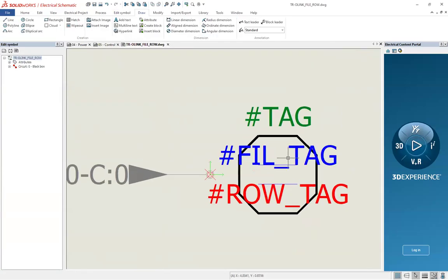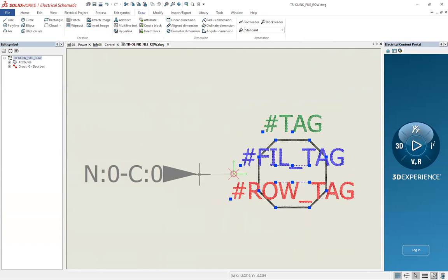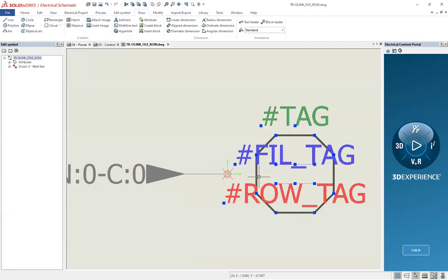And then what I'm going to do is grab all of this. I'm going to leave the insertion point, the red X. When you go to insert this, this is the point where your mouse is basically going to be, right? And I kind of want that to be right here in the middle of this line. So I'm going to move it.